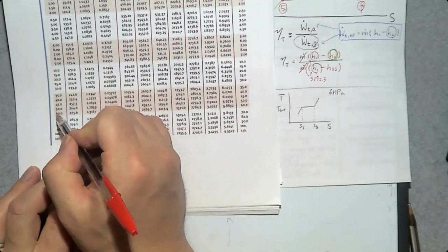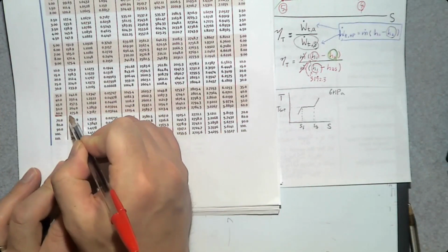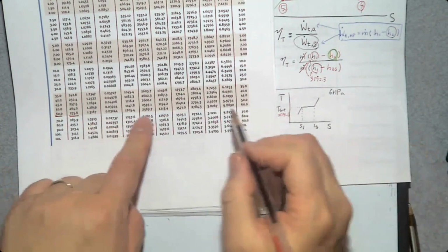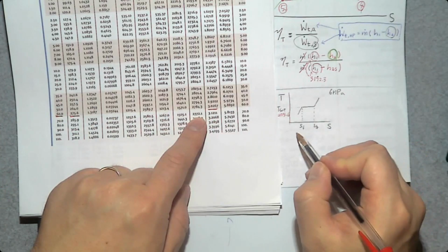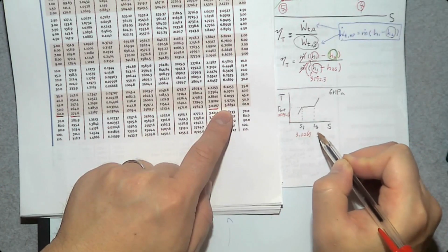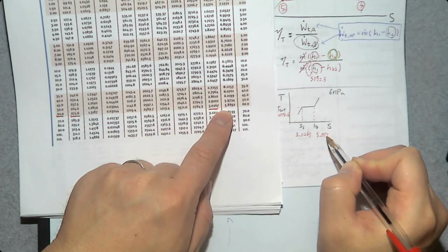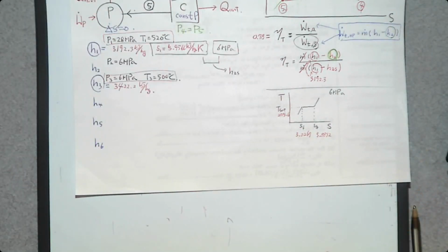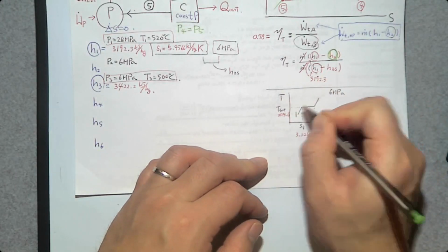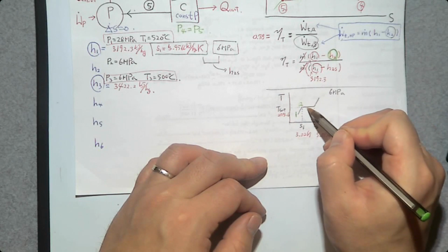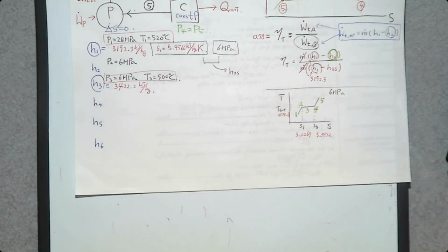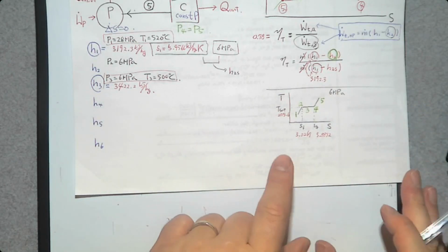It's right here. 60 bar is 6 megapascal. T_sat is 275.6, and s_f is 3.0267. s_g is 5.8892. And on this T-s diagram, we have compressed liquid here, saturated liquid, saturated mixture, saturated vapor, and superheated vapor. And now it's time to determine the phase change process.